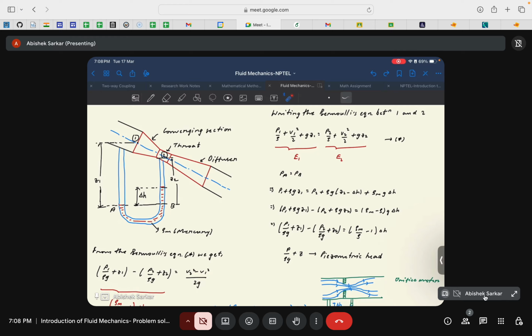But in this case, since the flow is decelerating, there might be a tendency for the flow to not follow this abrupt change in the cross sectional area. They might just go in a straight line rather than following this abrupt change in the curvature. You can understand because the flow is decelerating in its diverging section, so there is a higher chance of flow separation. So in order to prevent that, you usually reduce the diverging angle of this diffuser, so that the flow can properly follow the curvature of the diverging section and then move back to its initial profile.